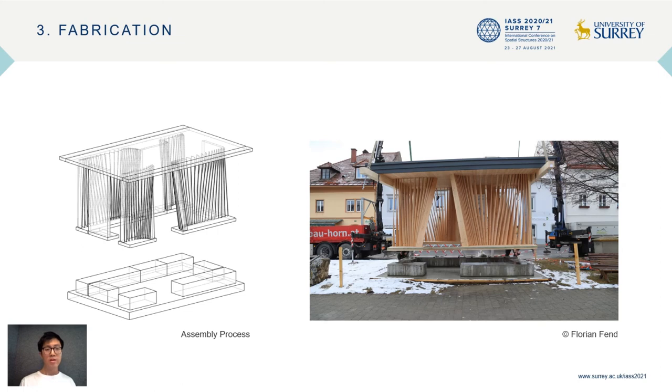It was decided at the beginning of the design phase that the timber elements would be entirely prefabricated remotely and transported to the subsequent sites. This meant the design of the typologies involved either splitting into multiple parts or maximizing them to the extent of transportable dimensions. The concrete pedestals and foundations were poured on site and the timber part was then mounted above.